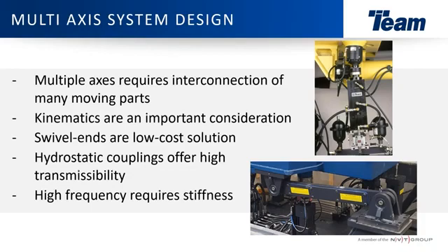And when you're doing higher frequency testing, it could cause issues with the fidelity of the test, as well as issues with the actuator over time, and the thin neck of the Hydroball here presents higher frequency issues once you get above 250, 300 hertz.